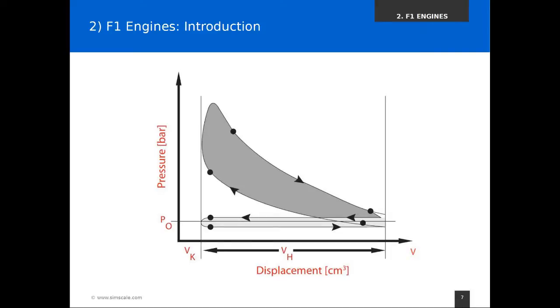The next thing that comes is the combustion. So we have that little spark set off by the spark plug, and this will actually trigger the combustion, the spontaneous combustion of our air and fuel mixture, which means that the pressure and temperature rapidly increase. Really, that goes within a very small fraction of a second, very fast. So what we do next is we go up the pressure line with almost no change in volume, but we really go up very far in terms of pressure. So the pressure now is super high, and this is now ready to be released.